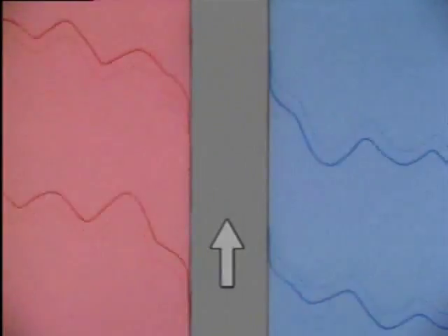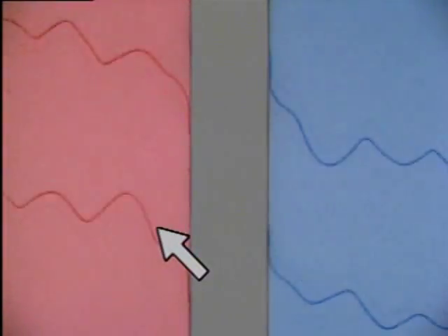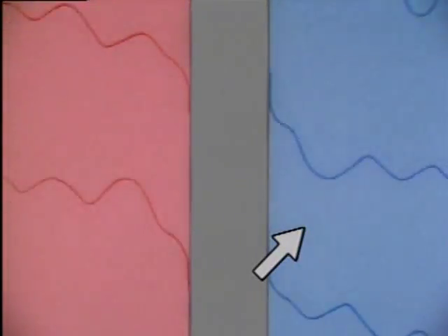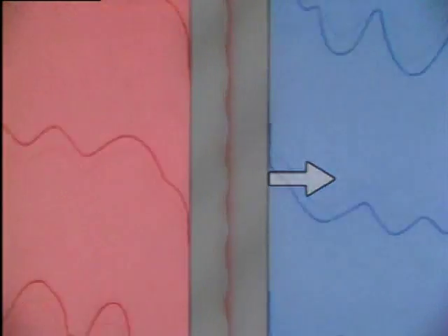Convection heat transfer occurs within or between fluids. Heat transfer between fluids often occurs when they're separated by a solid boundary. This represents a solid wall with a hot fluid on one side and a cold fluid on the other. Heat transfers by convection from the hot fluid to the wall. Heat then transfers by conduction through the wall. From there, heat is transferred by convection throughout the cooler fluid.